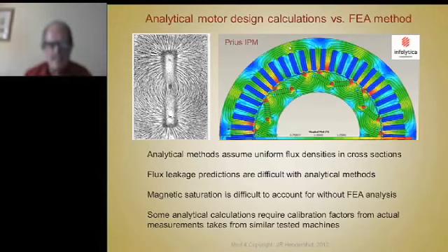You'll notice that if you see a solution where the lines aren't smooth, that means it had to jump when it knitted all the flux densities together, going along irregular connections of all those little elements because there weren't enough of them.